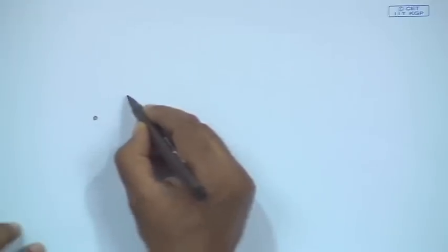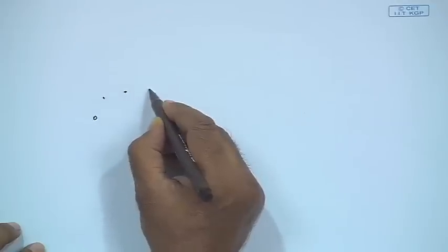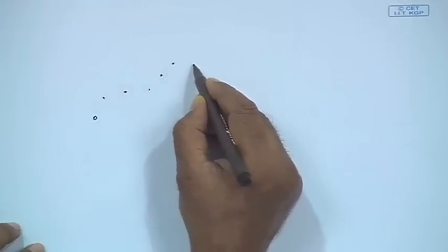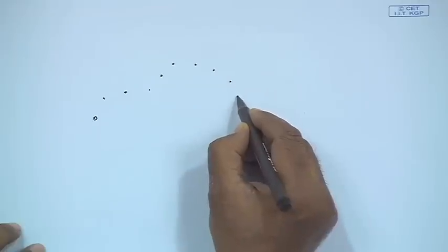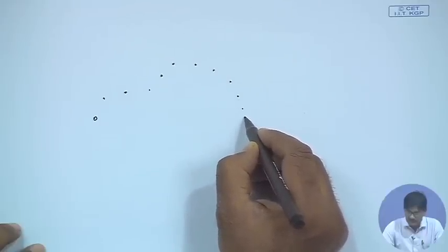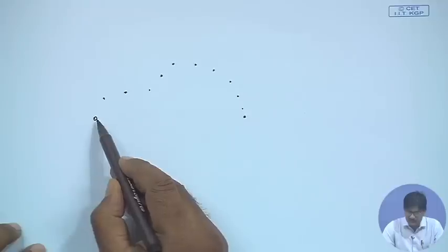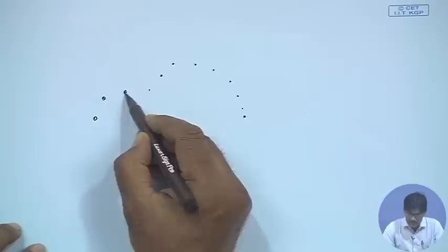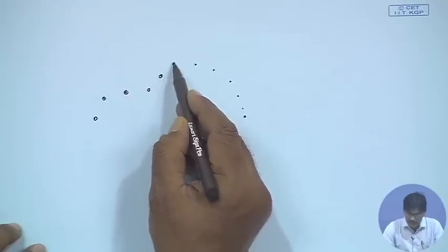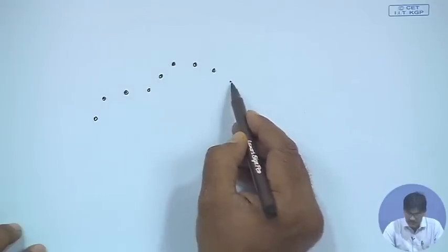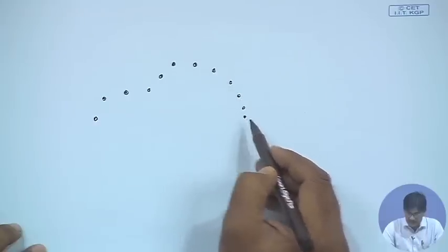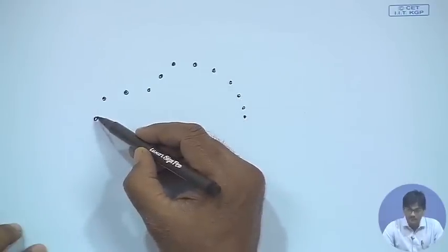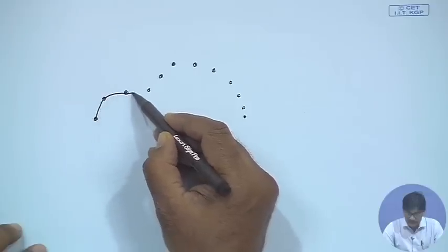Suppose a designer has designed a very nice looking car body, and he asks the person handling the geometrical aspects of the design to pass a curve through these points. These are not the control points, but points through which the curve has to pass, and after successful drawing, the Bezier curve could look like this.